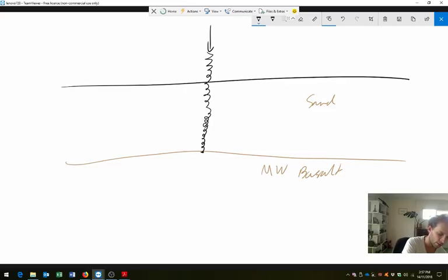Now, we're trying to push this corkscrew in. However, once we hit this hard basalt, it's going to be very difficult for it to penetrate further into the basalt. Because of that, it's actually going to start lifting out the sand faster than it's going into the ground. And you might say, well, why does that matter? It matters because we're going to start drawing the sand into this pile rig and flighting around the pile, which is obviously not a good thing.